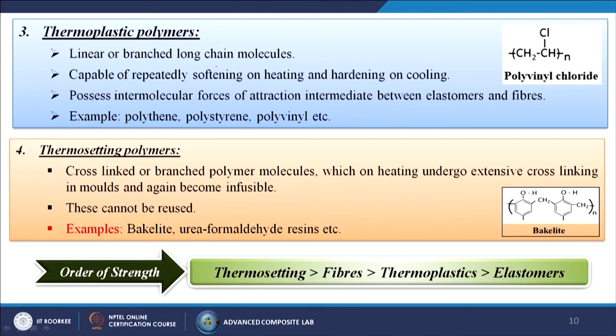Next, we are going to discuss the thermoplastic polymers. Generally these polymers are linear or maybe branched long chain molecules capable of repeatedly softening on heating and hardening on cooling, possessing intermolecular forces of attraction intermediate between elastomers and the fibers.